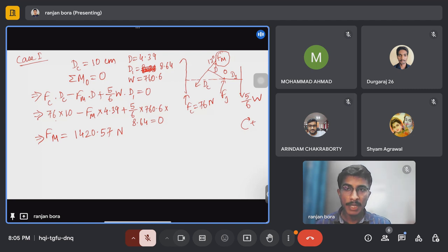In method one, we find the components of force along the x and y directions, and then we apply the equilibrium conditions, and using those equations we solve the unknown forces. In method 2, we use the vector method, which means we draw a triangle with the help of these force values, and using the formula of the resultant force, we find the unknown force in that triangle. Now we'll solve using that vector method.